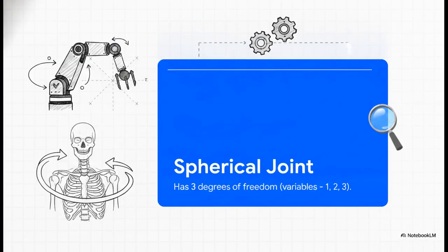And then we get to the real powerhouse of joint connections, the spherical joint. This is a highly complex connection that allows for 3 distinct degrees of rotational freedom, all happening at a single point. If you want to visualize this one, just roll your own shoulder around. Yeah, the human shoulder acts very much like a spherical joint. And from an engineering perspective, building and then mathematically controlling a joint that manages multiple rotational axes intersecting all at once is a tremendous challenge.